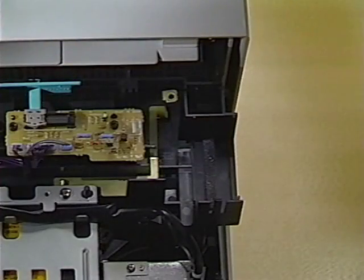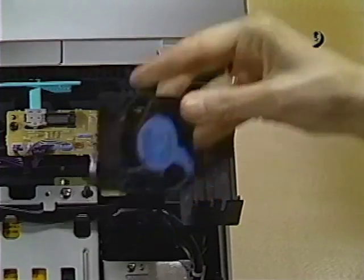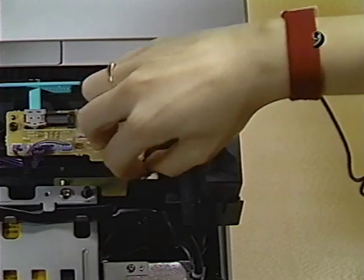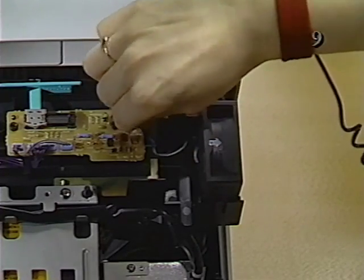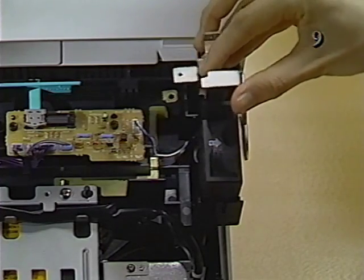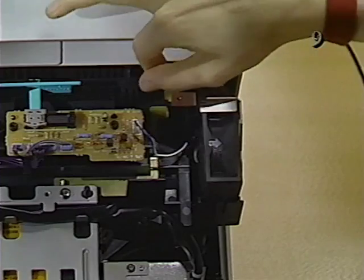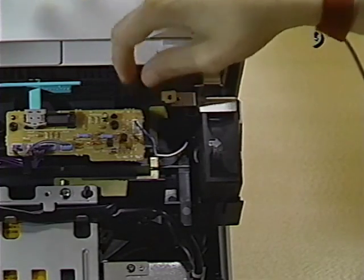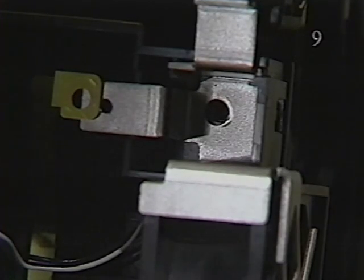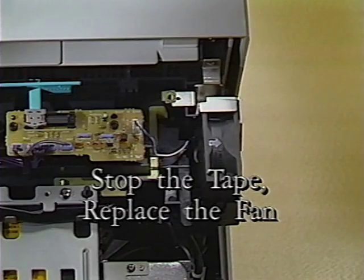Replace the fan. Start by sliding the fan into the plastic fan holder on the printer chassis. Reconnect connector J107 to the density adjusting PCB assembly. Now slide the left nut plate into position over the fan. Be sure to place the finger of the gold grounding plate over the left nut plate. Then replace the two screws that secure the left nut plate to the printer chassis. Stop the tape and replace the fan.